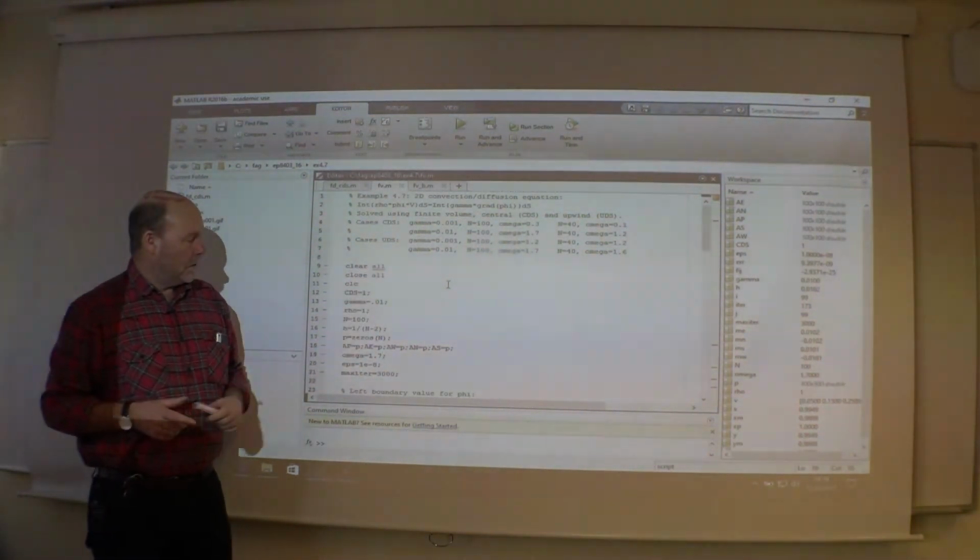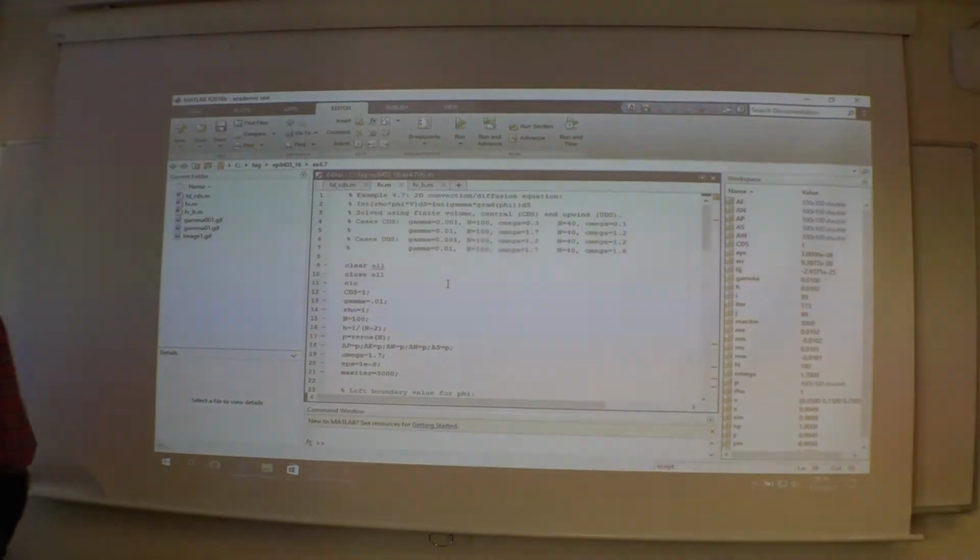Now, jumping to an upwind scheme, we could do the same. CDS 0. So if we go back to the first case here, now you see I can actually use a much bigger omega, finding a solution much faster because this one is much more stable.